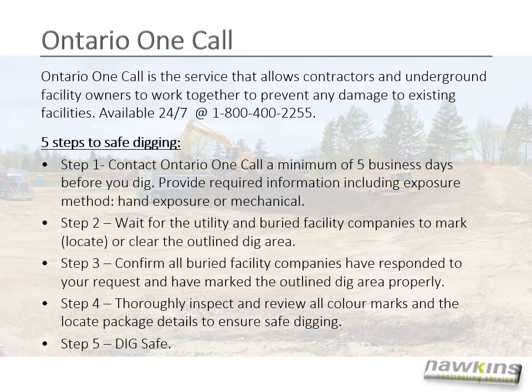Step 1 is contact Ontario One Call a minimum of 5 business days before you dig. Provide required information, including exposure method, whether it's hand exposure or mechanical. Step 2, wait for the utility and buried facility companies to mark, locate, or clear the outlined dig area.